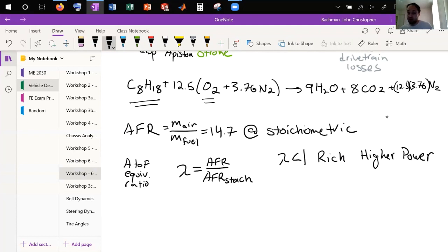So that's just basically making sure you're burning all of your air, which is what's really limiting you in terms of how much fuel you can burn. But then you're kind of wasting fuel typically. You're really leaning towards getting a high power density, or just high powers out of your engine, at the expense of dumping in extra fuel.